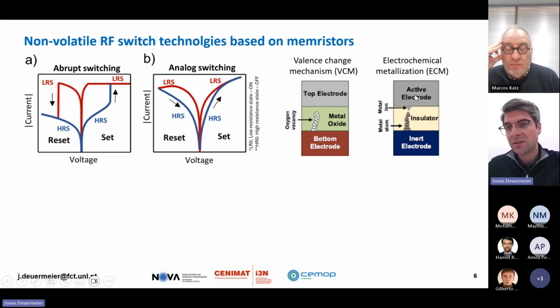So the metal can be dissolved at one electrode, migrate through the insulator, and redeposit on the other electrode, forming a filament, which then connects and disconnects at a small junction. And this Joule heating ruptures the filament just by increasing the local temperature, and this increases diffusion and makes these metallic atoms essentially rediffuse into the matrix.